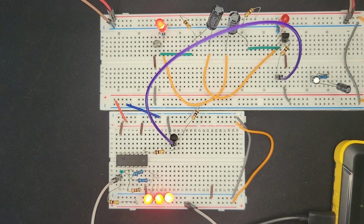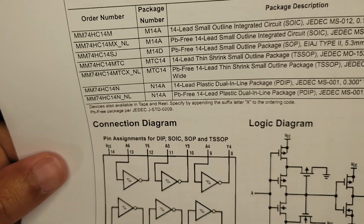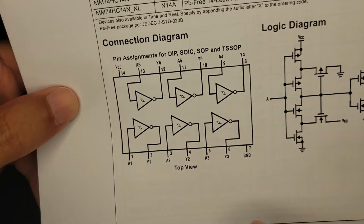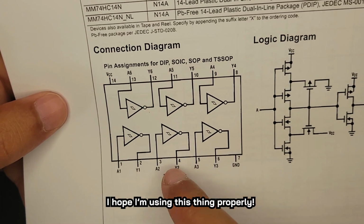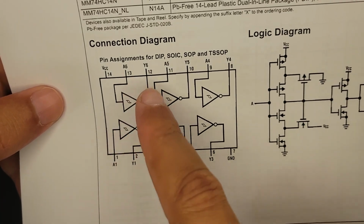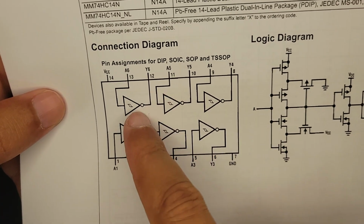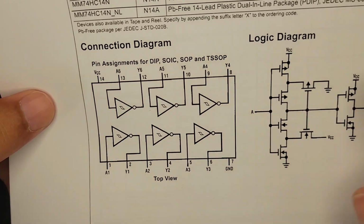So I'll be right back. Okay, so we have a Schmitt trigger, which is supposed to clean up the signal and create a perfect square wave. They look kind of like hex inverters because there are 6 of them, just like the inverter chip. We just put in the power and the ground, and each of these inputs will give us a clean output. So I'm going to use the top one, A6, the one next to VCC, and then our output will just be the one next to that.